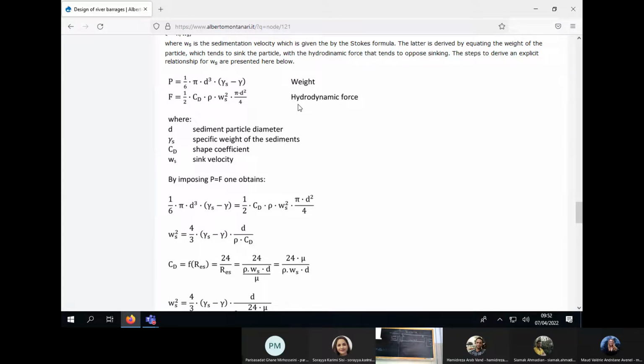If it's very shallow water, then sedimentation is easier. Second, people may fall in the sand trap, so if it is very deep, then it may be dangerous. Sometimes we have the upstream tank that is very deep, and then you have to protect it to avoid that people accidentally fall in.